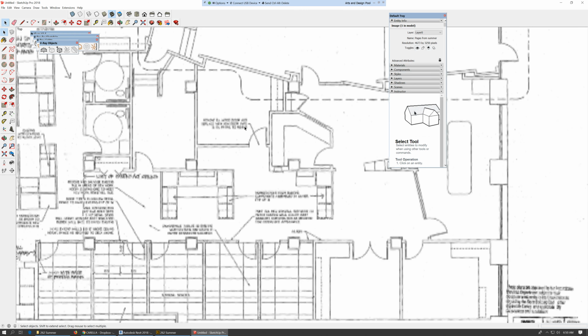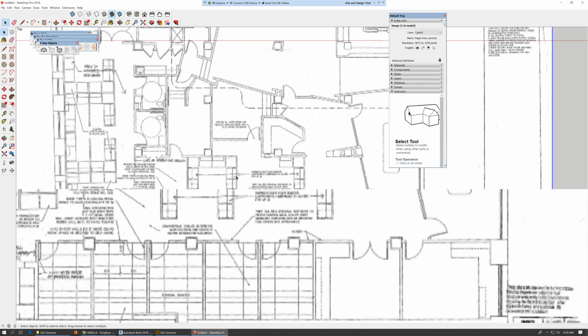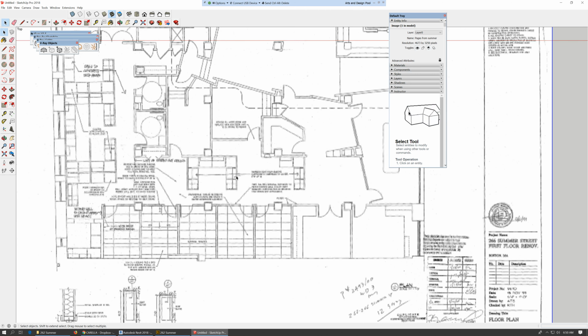The quality of the preview image is poor here, so I'm going to pause the video and find the dimension, and then come back and resize this drawing according to that dimension. You want to use the largest possible, like from one end of the building to the other. Preferably, don't try to resize from a door, because the margin for error is way too large if you're working with a small measurement. So 3 feet isn't going to scale, but the 25 feet between these columns, or 50 feet between two of them, is a much better metric. I'm going to pause now.